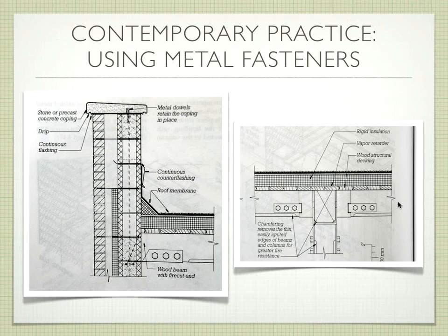The tricky thing is that this steel also comes down and attaches to this column. So this steel wraps around here, and it's also welded such that one side, I forget which way I was doing it, it'll be this side, has a steel plate that comes down like this. Underneath, that's bolted, you see the bolts right here and here, through that column. So that fancy steel piece is what's allowing us to have this kind of connection, and it's also staying stable and very rigid, so it's handling lateral loading as well.